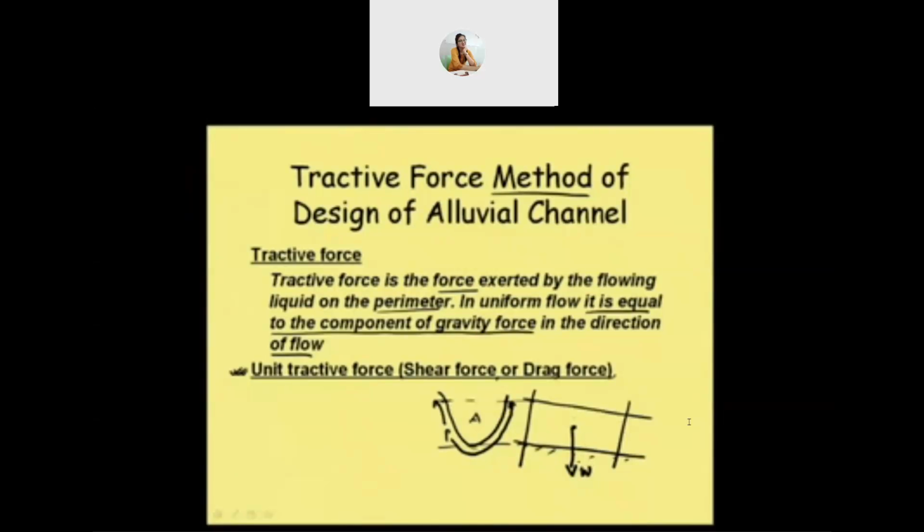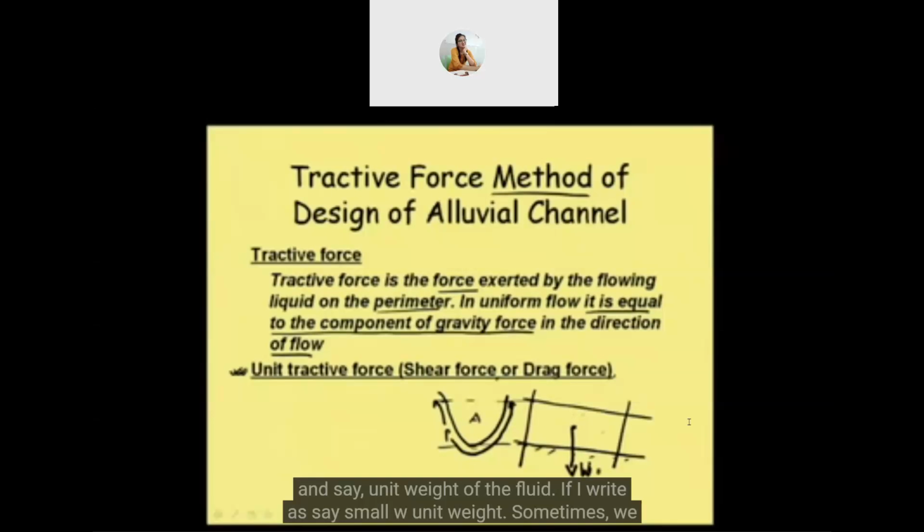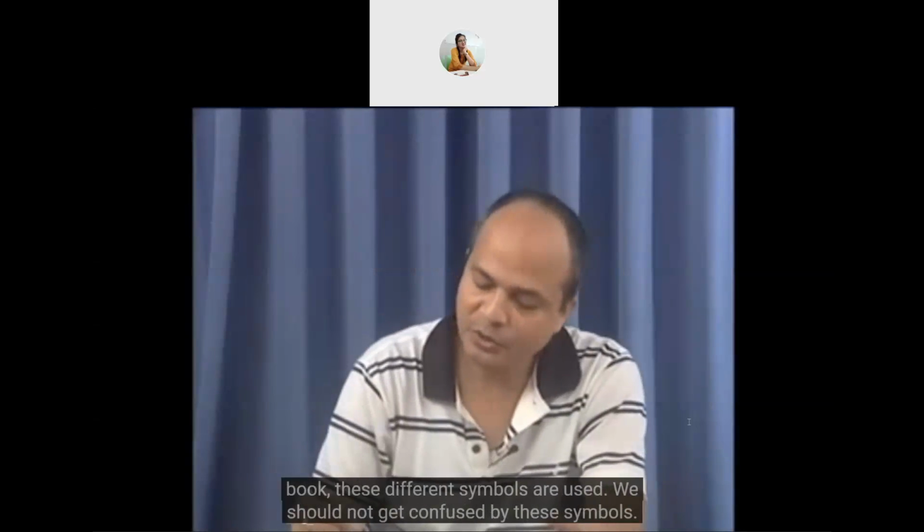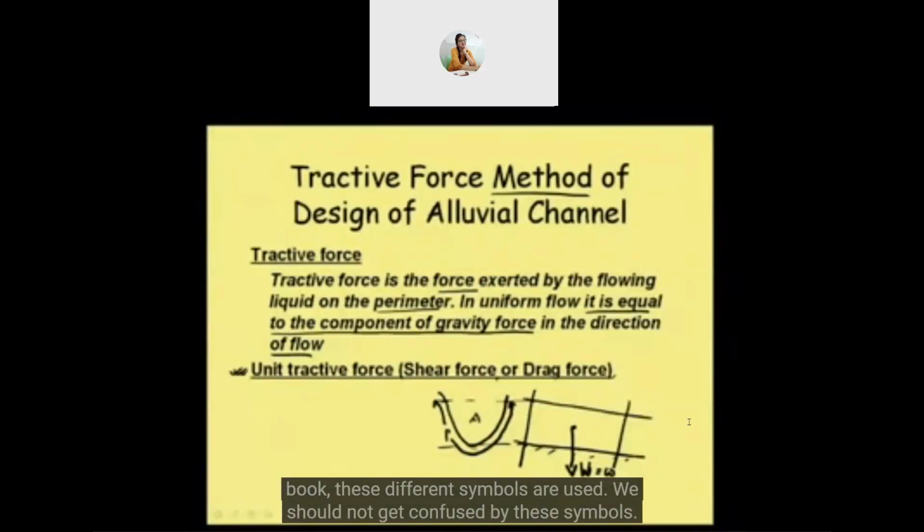If I represent this W as the total weight, and say the unit weight of the fluid, if I write it as small w, sometimes we use the term gamma W to represent unit weight. In different books, different symbols are used. We should not get confused by these symbols. We should know the physical meaning of this one. So it is the unit weight of water if we write. Then unit weight multiplied by the volume of this fluid.